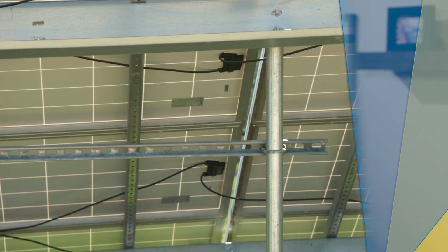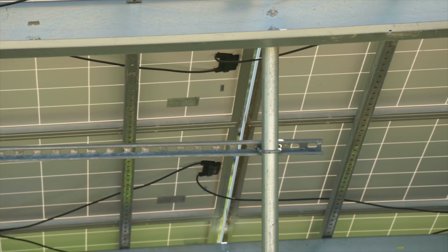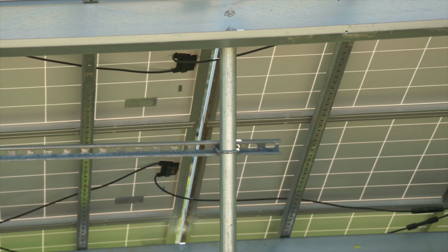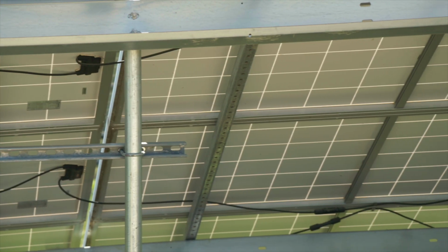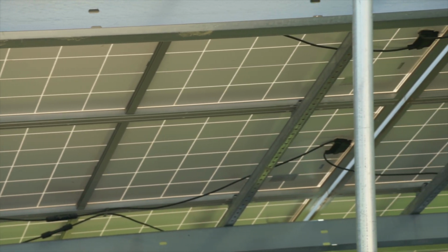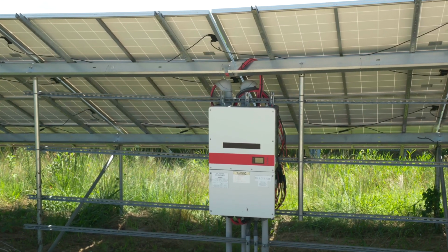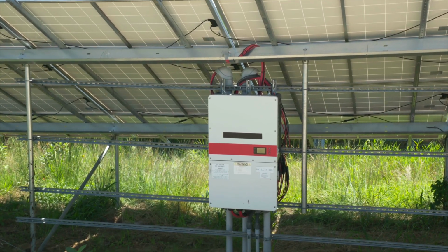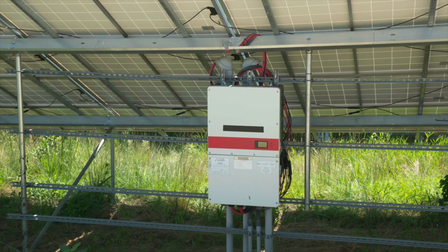Steve, help us then again, how does that get from those modules into usable electricity? What's the next step in there? So behind the modules, it's a lot of DC wiring. That's bringing the power together, DC, similar to batteries. And we bring that up to our desired system voltage. On our larger systems, that's 1,000 volts DC.